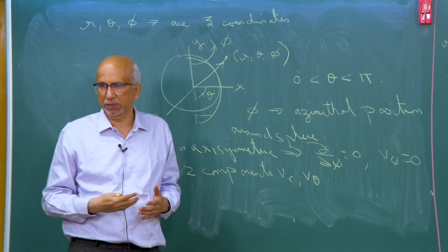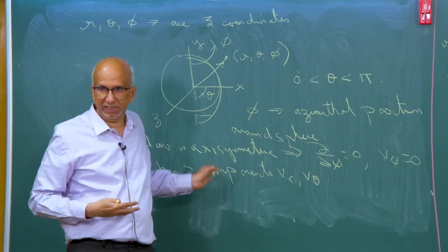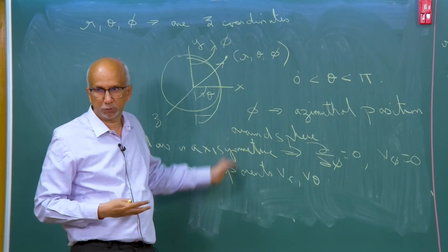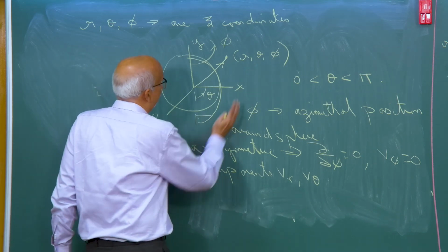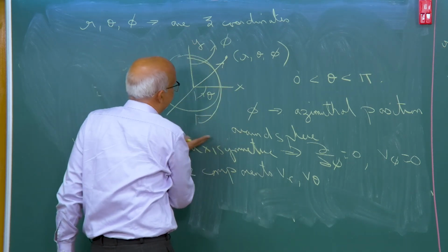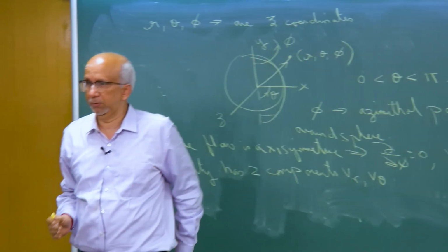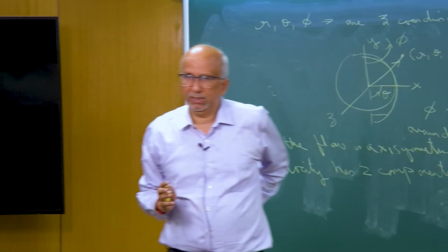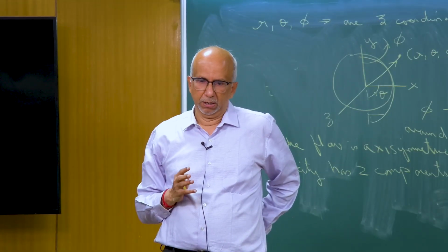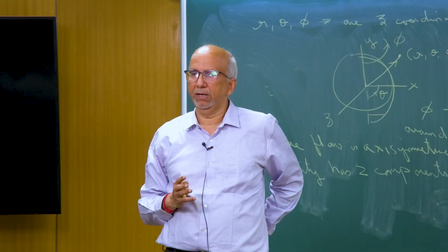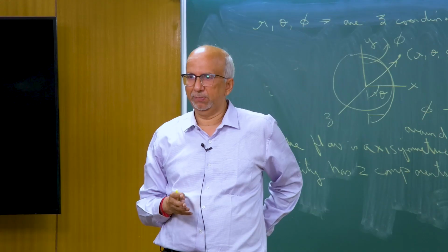So the radial velocity is definitely changing with the radial position. As it comes closer, velocity is going to change, and as it goes around like this, the velocity is going to change because of the theta direction, then it goes back to getting V infinity. So basically the point is, in this coordinate system, the 2 independent variables are r and theta. And the 2 dependent variables are Vr and V theta.